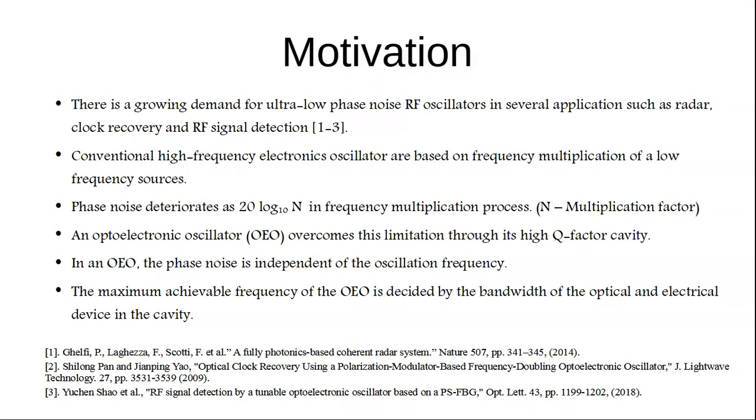There is a growing demand for ultra-low phase noise RF oscillators in several applications such as radar, clock recovery, and RF signal detection. These RF oscillators are based on frequency multiplication of a low frequency source, due to which phase noise deteriorates as 20 log n.